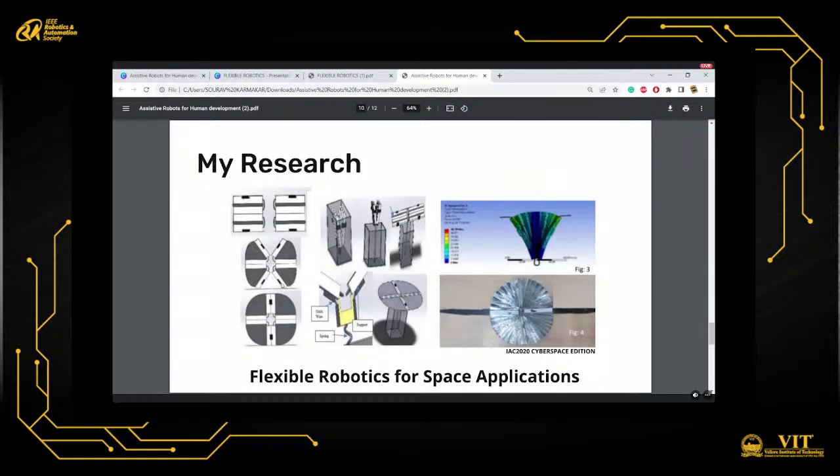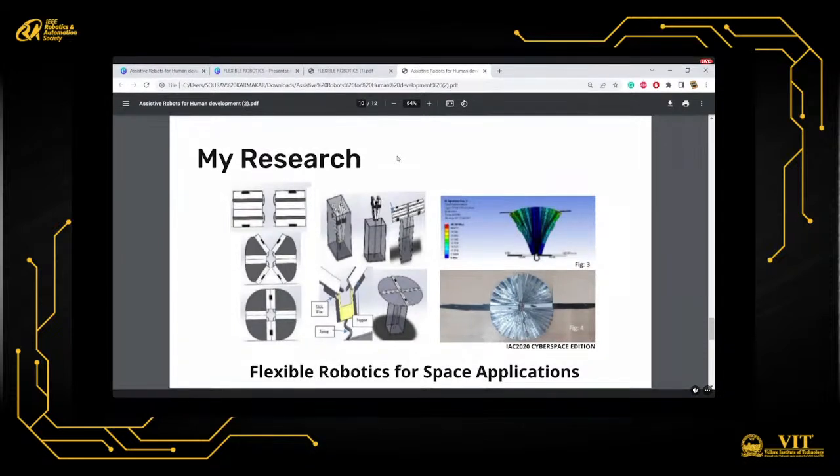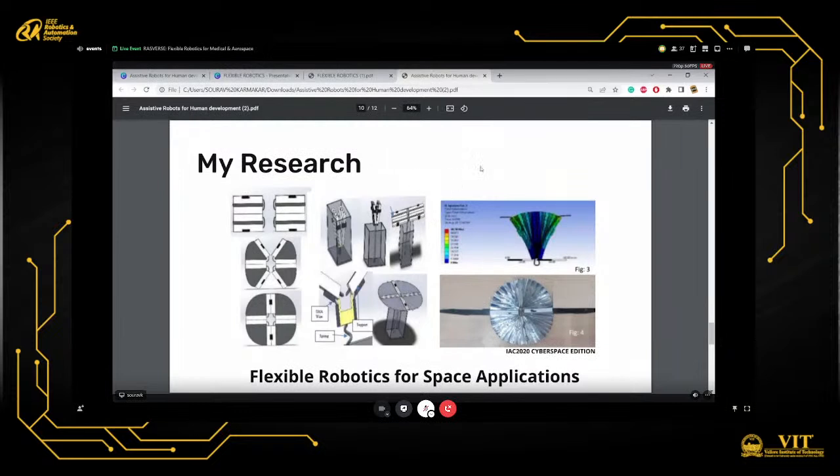It's basically that kind of mechanism we developed, and here we have not used a single motor or any rigid body actuation or any kind of motor for rotation. My whole principle is to use a soft robotic actuation system. Soft robot actuation is not only from pneumatics or liquid; it can also depend on compliant actuators, flexible actuators. One of the very famous actuators is SMA, shape memory alloy, made of nickel titanium. It has different alloys, but the most famous one is the nickel titanium alloy. So we have taken around 1 mm diameter SMA wire,